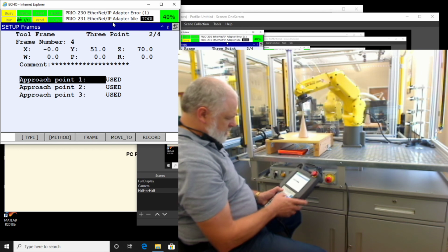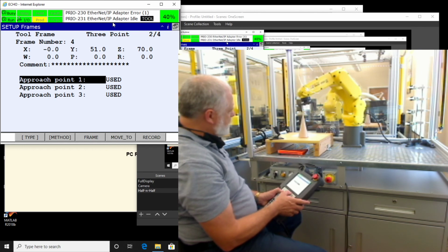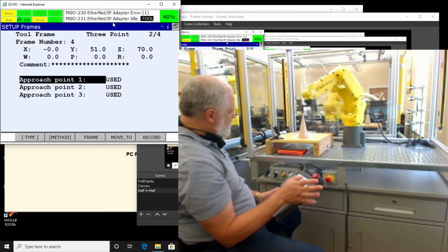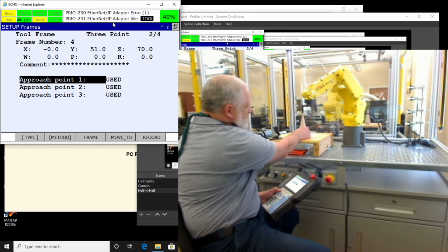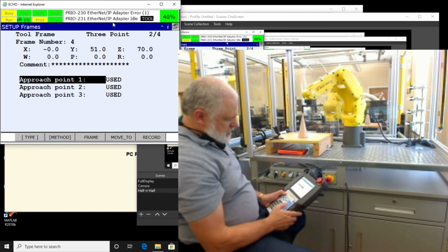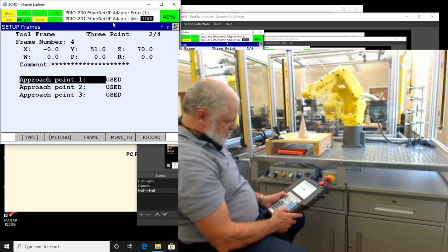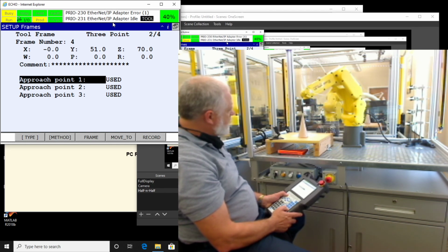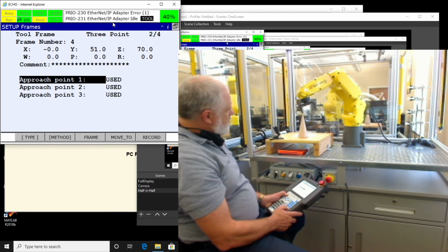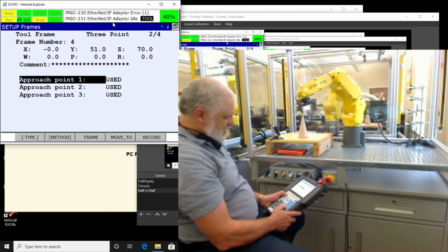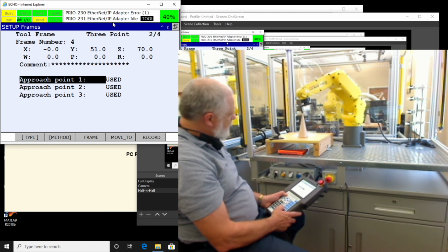Let me return. I'm going to do a move to get back to my point there. I didn't mean to change X, Y, or Z. I just want to change the yaw, pitch, and roll. So I'm just going to jog yaw, pitch, and roll, and I bumped Z there. Okay. So you see that the right pointer is moving all over the place, but that left one is sitting right there.